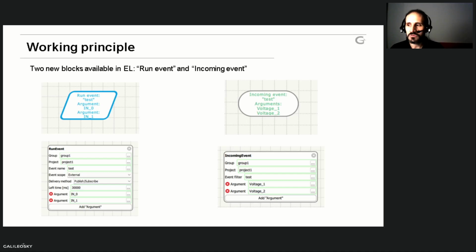You can use this block just to get arguments, just to get variables from the other device, but you can also execute commands, right? You can use it as a normal command block. So after starting the reception of this incoming event, you can execute some actions, open or close an output, maybe turn on some bulb, maybe make some machine run. It depends on what you are planning to do, or maybe send some data. It depends on you.